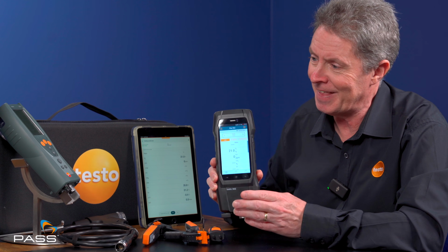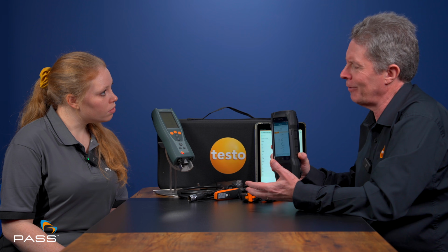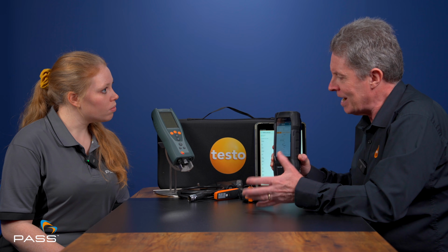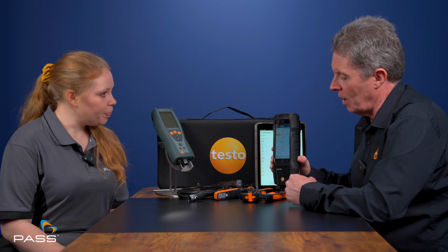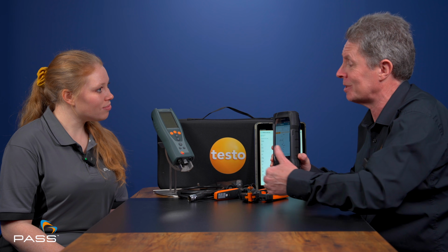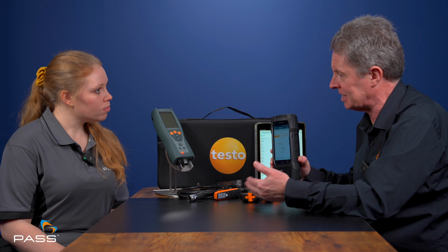But also, more importantly, the LL has an auto dilution function. It's quite important. When you're talking about a flue gas analyzer, its key aspect is it's being used for combustion readings. With any boiler, there's always the potential for a CO spike or a high CO level. Normally, that can be the kiss of death to an analyzer, because if you take the analyzer to its maximum CO, you could be lucky and get it out into fresh air and do a rinse cycle and flush that CO out of the sensor. But in a lot of cases, the damage has already been done.